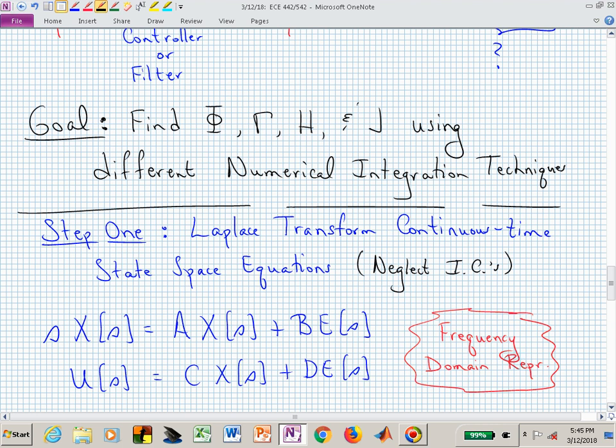What did we do before? When we were in the transfer function setting, when I gave you a G of s, and you would need to then hand me a G of z, how did you give me the G of z back? What did you do? If I said the forward approach, you would simply replace every s in that G of s formula with z minus 1 over T.